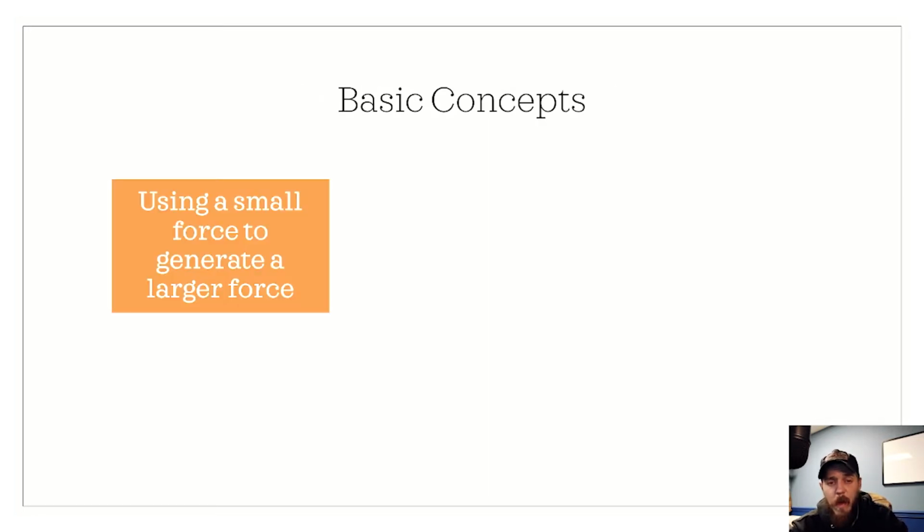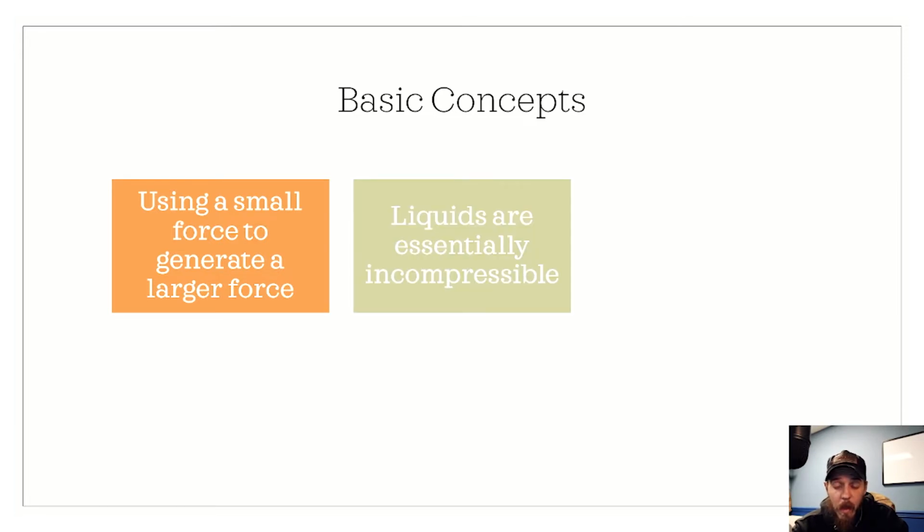Most basic concepts of hydraulics. Really, if we were to distill it down to the essential concept and what we're really doing, we're using a small force to generate a proportionally larger force, generally an exponentially larger force. We have to understand that liquids are essentially incompressible, meaning when we try to compress fluids, they don't compress like air does. They don't get tighter, they don't get smaller. The force we put on them is applied elsewhere in the container.